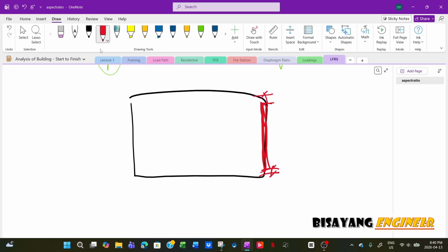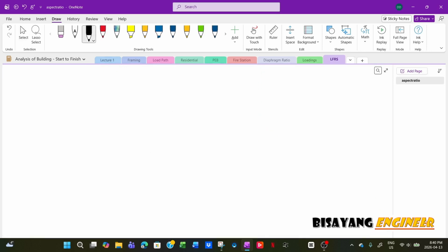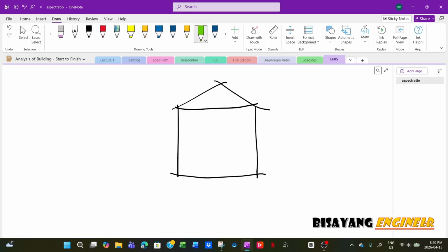If you look at the elevation, for example, this is your building, then there's your roof, and then they want a large overhead door so they can fit big trucks going in and out. So this is an overhead door. There's no more room here for shear wall.